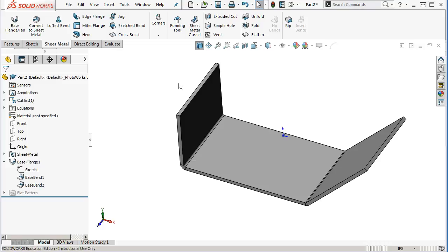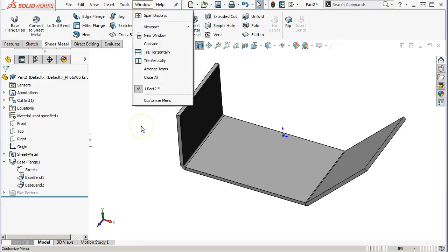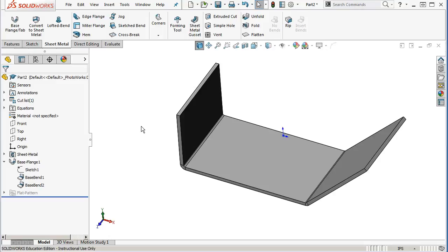But really, what is the purpose of this document? It is to get us consistency, have tolerance control, and make sure all of the parts are within a reasonable manufacturing process. So, yeah, it would be a discussion. We would have a discussion of why those flat pattern dimensions are for reference only.